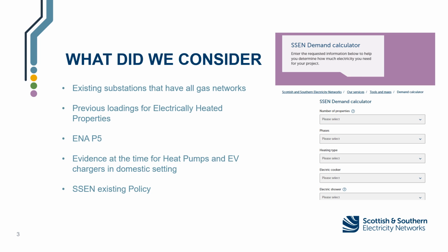So SSEN decided to adopt and use the input powers for the heat pumps and not to reduce this. This way, we were using the input power per heat pump, which means our ADMD calculates it out based on the heat pump rating of the heat pump, rather than the output heat of the heat pump and using a temperature coefficient, which might not accurately reflect the input power of the heat pump. Sometimes that may be less, sometimes that may be more.